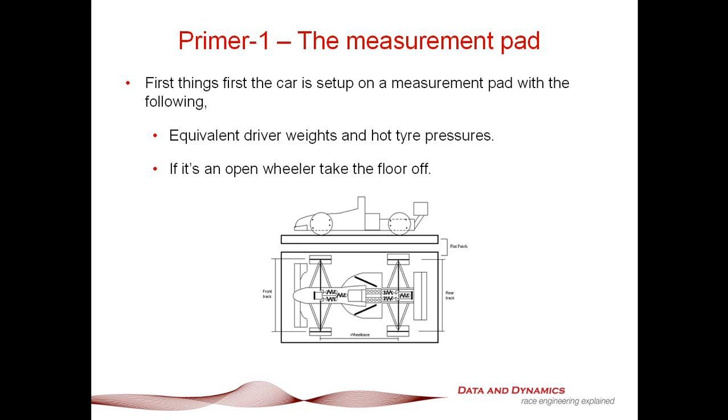Both myself and some of my colleagues have been placed in this situation, and I can tell you right now that all you need to do is basically have good attention to detail, know what you're measuring, and also have a very good awareness of the numbers. So that's our first primer, making sure that we've got the measurement pad so we can get our suspension geometry pickup points appropriately measured, and we can get things like our tracks and our wheelbases measured.